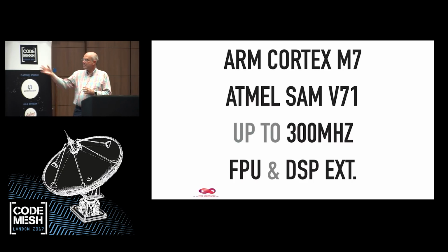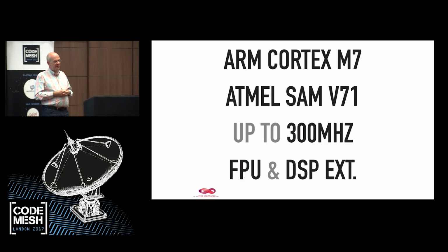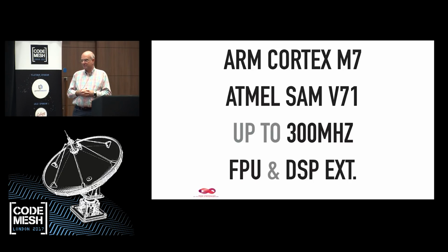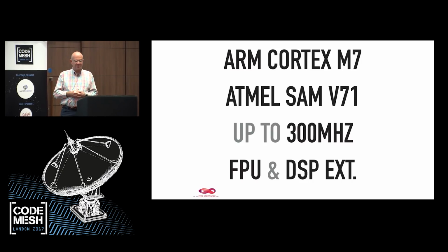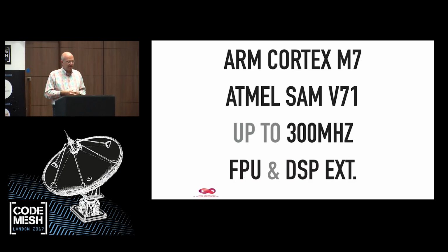And it has a built-in FPU, which is kind of convenient, since Erlang kind of expects that there's an FPU. Not every embedded processor has an FPU on it. Lots of very small ones don't have an FPU, so you have to use a software FPU. And then better don't do too much calculation, because software FPU is very, very slow. And it has some digital signal processing extensions, which we plan eventually to actually map to the Erlang side with NIFs, so you can actually use them for little signal processing things or calculations for control loops or whatever.